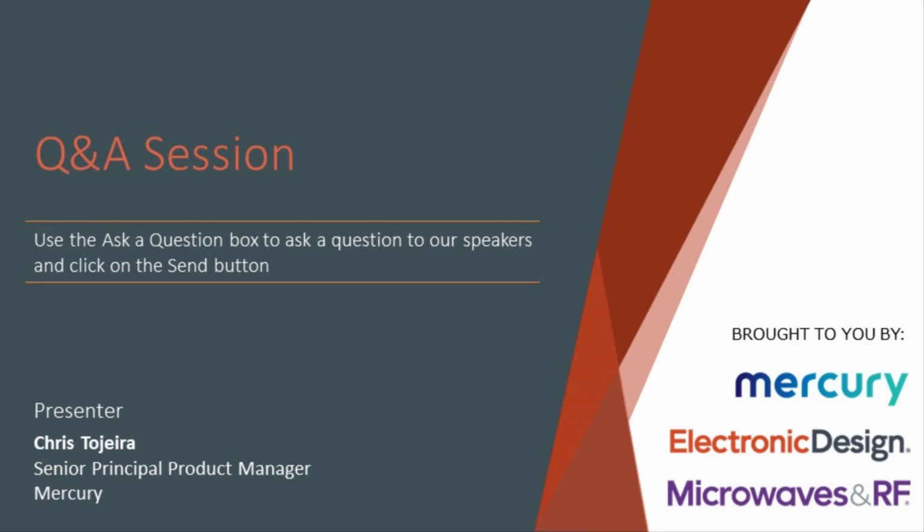If you want to start working with actual Versal hardware and get hands-on experience, you have a few different options. Mercury has a COTS 6U VPX OpenVPX board called the SCFE 6931. The board's available today and has two Versal AI Core parts. It also has 8 by 4 lanes of optical, so you can actually run 800 gig interfaces in and out, which is the kind of data throughput you need for the kind of processing you might want to do.